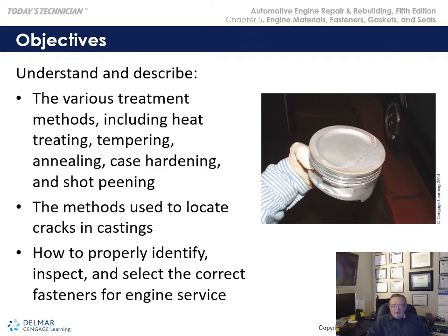We have various types of metal processes that happen from the time they take raw material to when we get a finished product ready to ship out. And that includes a variety of heat treating methods. Heat treating can be done in an oven, but it can also be done with electrical probes that come down and attach themselves to metal parts. They do that on crankshafts. Crankshafts will have the critical portions of the lobes and the journals heat treated, and you can see that in some crankshafts today that have bluing around the critical parts.